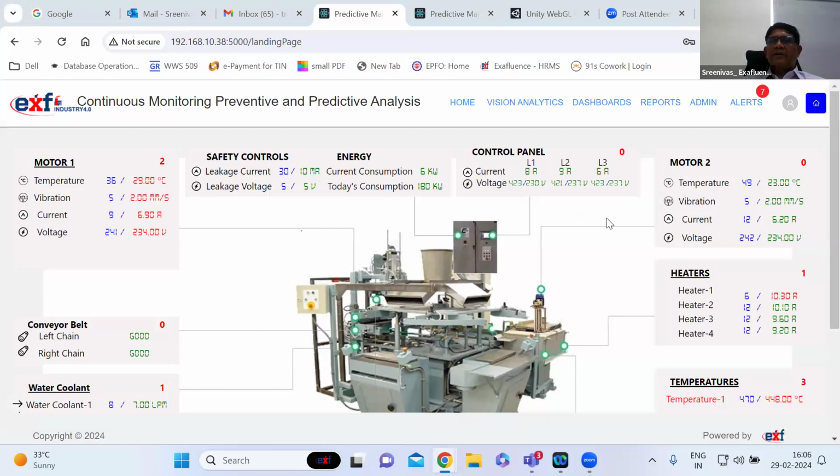There is a shaft which is driving the motor, and there is a bearing inside the motor. Once we have any problem in the bearing, and the speed of the bearing is irregular, it will take more torque. The more the torque, the more the current being drawn.